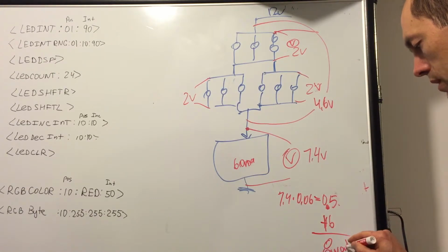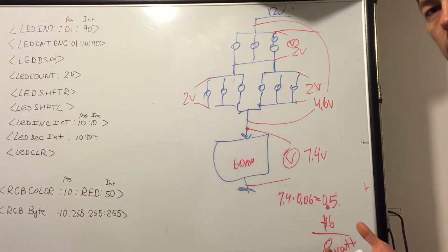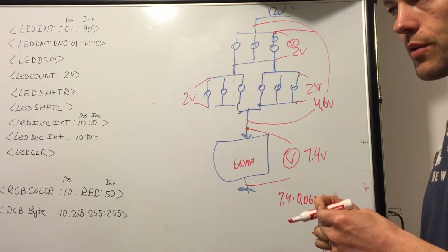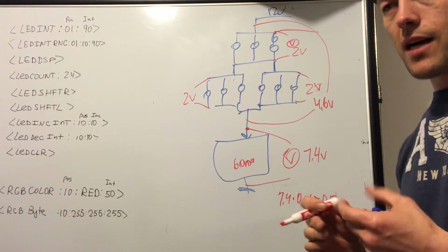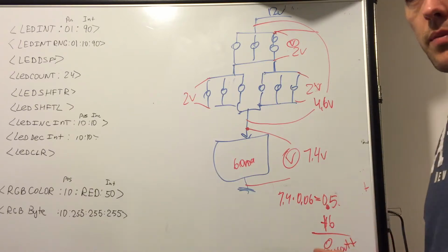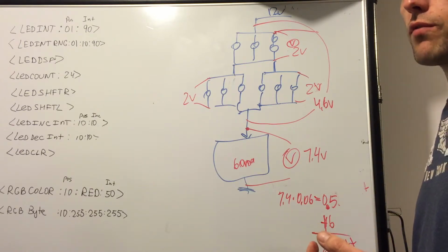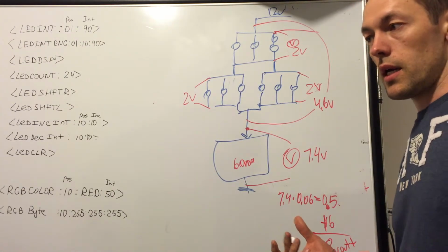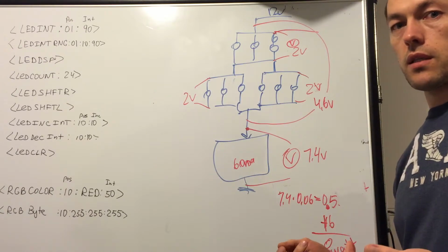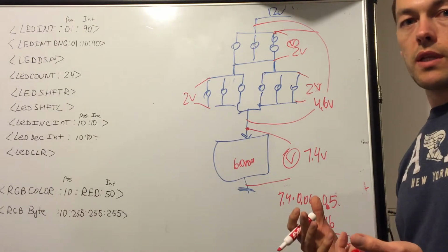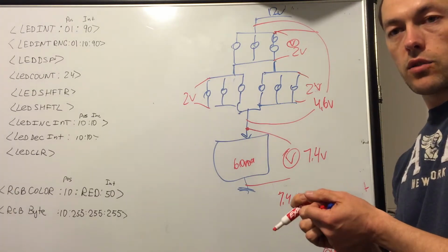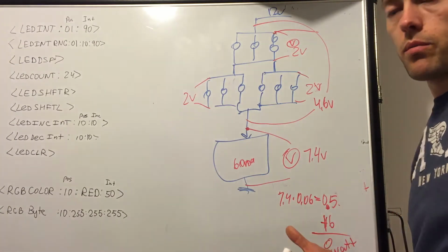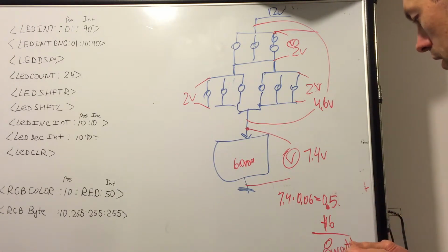And it can't support 10 watts. I can't tell you right offhand what it would support. The chip itself is pretty small, and it sits on a PCB that dissipates some heat, and it's copper, but it's not much. It still can dissipate 8 watts. Think about this: 8 watts would be if you take a small bulb for automotive or motorcycle use and light it up at 8 watts, it doesn't produce a lot of light, but it produces a lot of heat. And if heat's gonna stay there, it's gonna collect that heat over a period of time and get hot, and the bulb doesn't burn because it's glass, but it burns electronics.